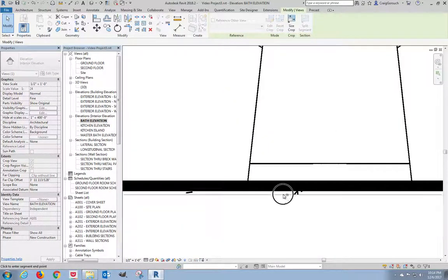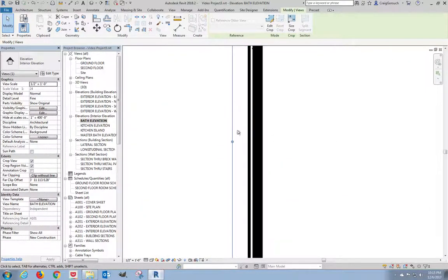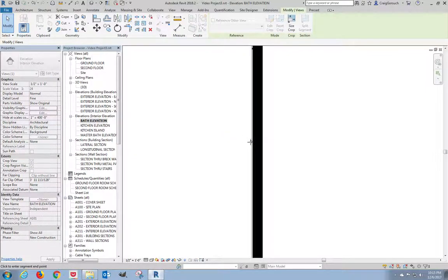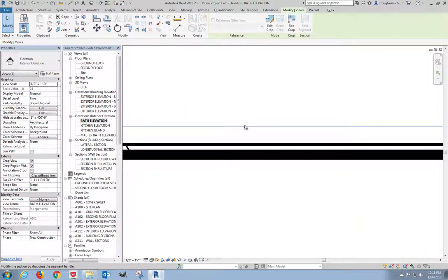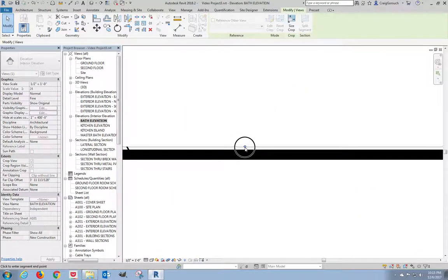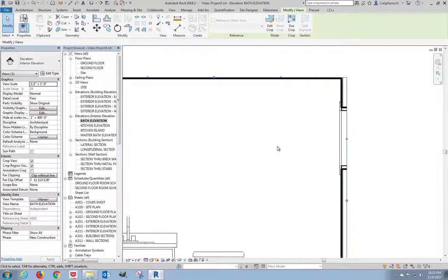This is the only way to fix this problem. You just have to zoom in, grab the dot that represents the edit grip of our viewport, and just manually modify it so that you can see the thickness of the line. It's a weird thing, but it is.